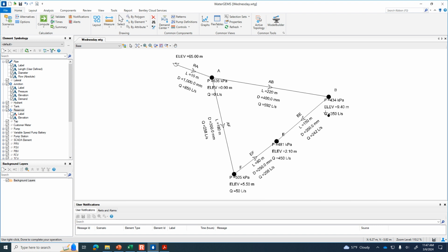So let me ask you this. Is the network oversized? What do you think, Matthew? Are these pipes bigger than they need to be? Yeah. How low is the pressure allowed to get? What's the minimum pressure that's allowable? Javanti's close, 240. So we can go as low as 240. Are we close right now?